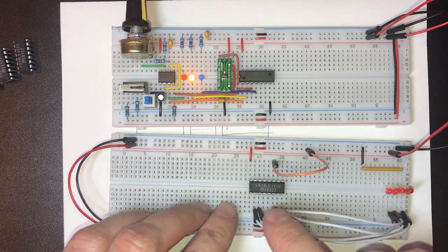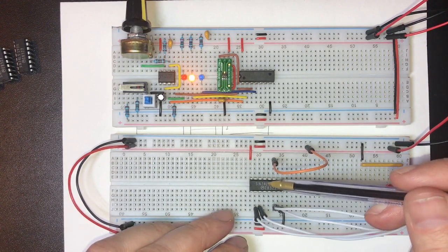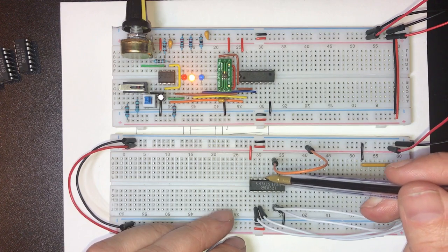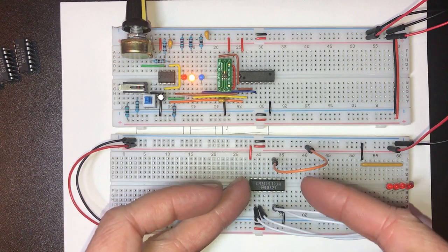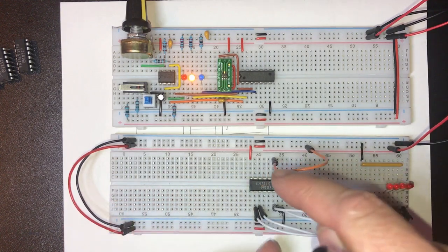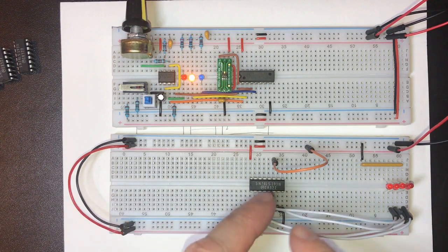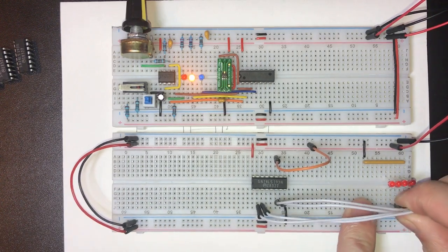One thing I do like about these chips is the count up and the count down and carry up, carry down are on opposite sides. So on a circuit board it would make a lot of sense to rotate these chips by 90 degrees, and then you could put 4 of them in a row and just have the carries going straight across. Okay, I've misaligned those.